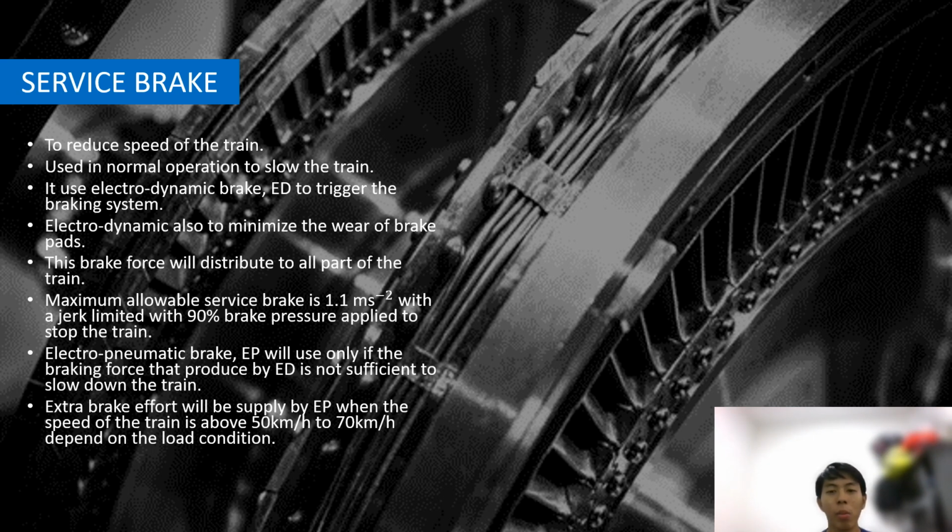The maximum allowable service brake is 1.1 meter per second square, with a jerk limited with 90% brake pressure applied to stop the train. The electro-pneumatic brake (EP) will be used only if the braking force produced by ED is not sufficient to slow down the train. Extra brake effort will be supplied by EP when the speed of the train is above 50 km per hour to 70 km per hour, depending on the load condition.